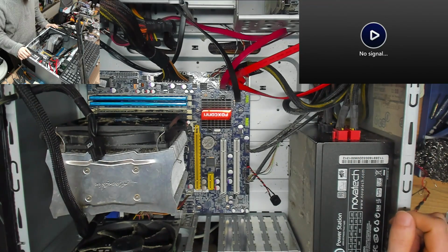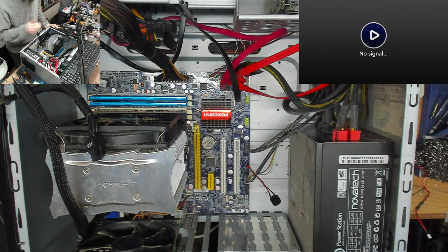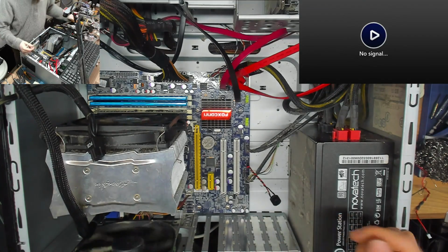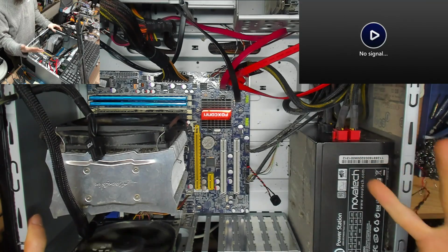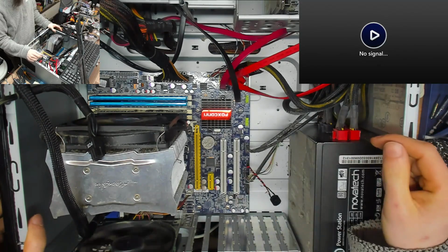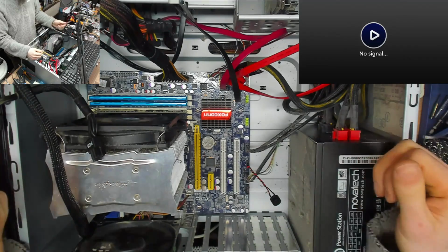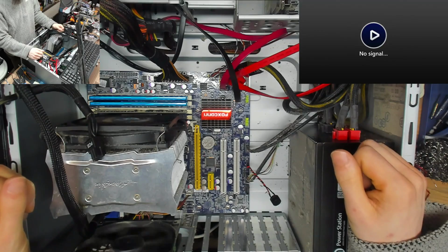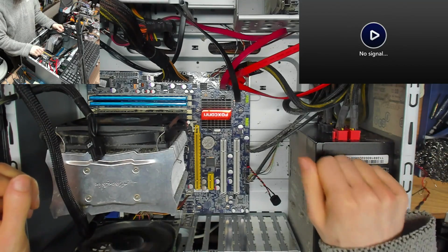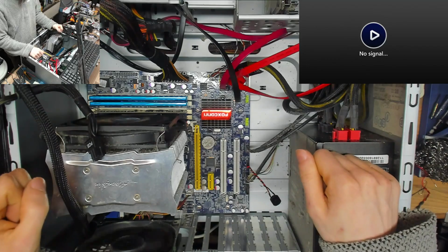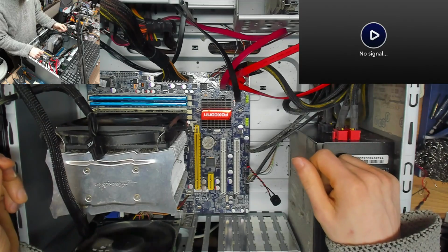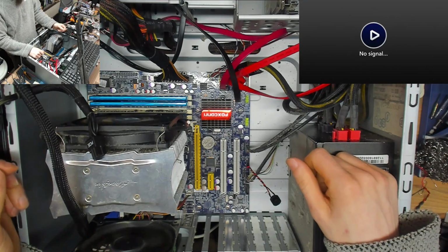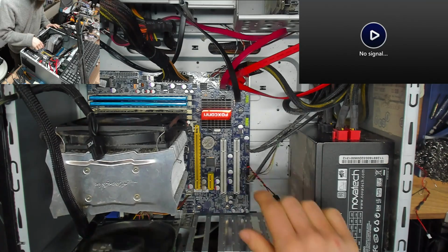Right. Okay, let's try that one more time. Power on. And it hasn't turned on by itself that time, so let's try it again. I think we're going to be doing a BIOS reset in a sec, although I'm not expecting that to make any difference because it's an intermittent post. If we had no post, I would have gone straight to the BIOS reset, but this intermittent posting is really causing an issue. It looks like we've cleared the power supply at this point because I'm having issues while we're on the Antec. And we're getting no beep from this, so we're not posting. Okay, I'm going to turn it off and we're going to do a BIOS reset.